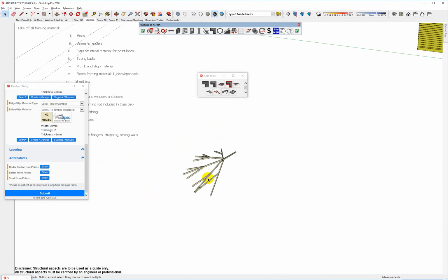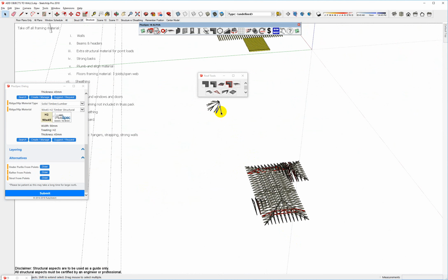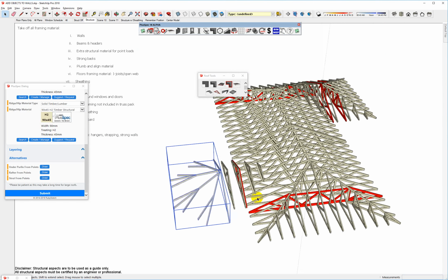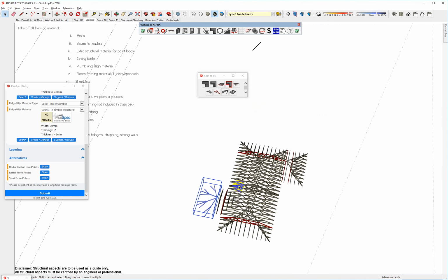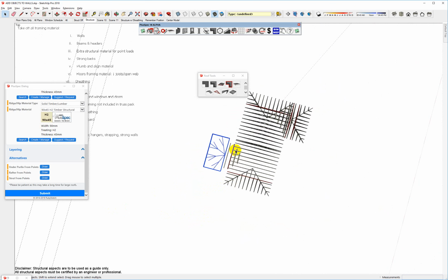So look, there's a whole heap of ways to add stick timber to rafters without any dramas. You can obviously move it to where you want it to be. It's grouped. Move it to where it was going to be here, just say roughly like that. Bang, I now have a roof. I can create a layout from here. So I might say, well, I want this to be top down and I want to label it.